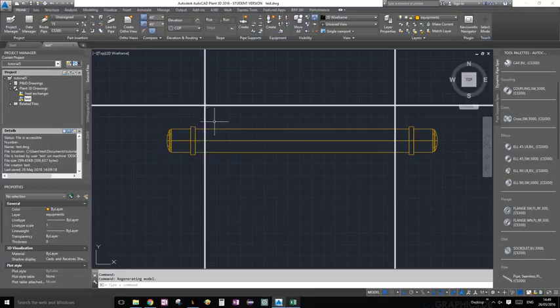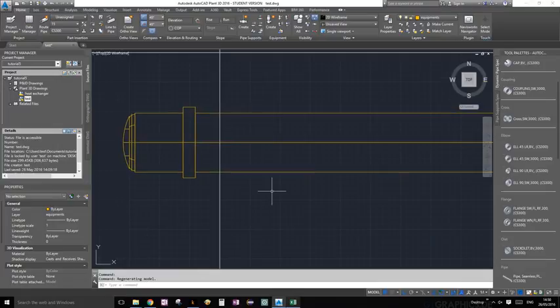So you could have said, for example, the center point of the support for the heat exchanger is 600 millimeters away from this horizontal grid line, and centered on the vertical one. Then you would have known exactly where to put it, and you would have put your heat exchanger on top. But here we don't, so we're just going to approximate a position. I figured that out a little bit, so that should work.